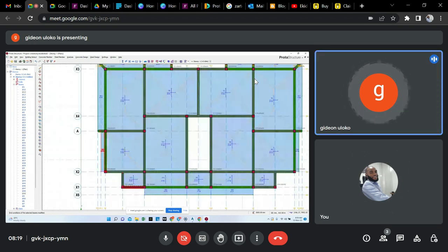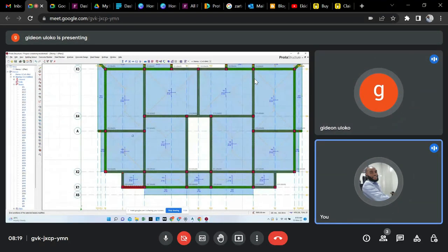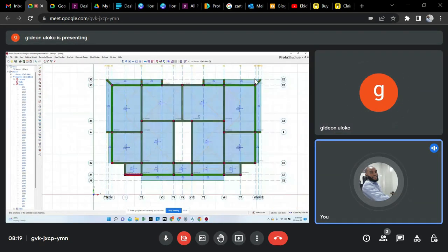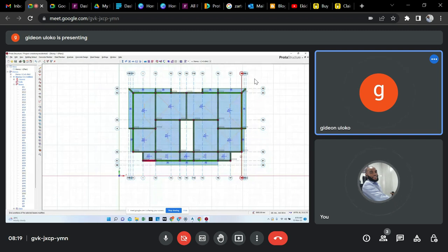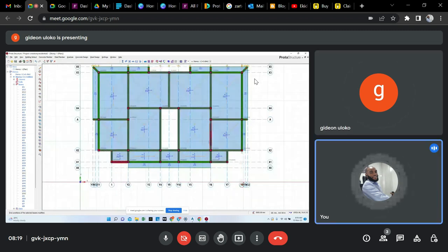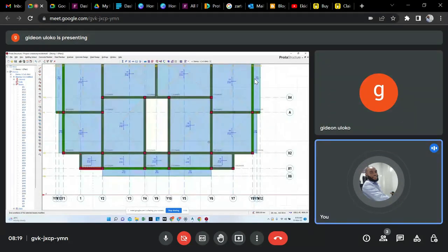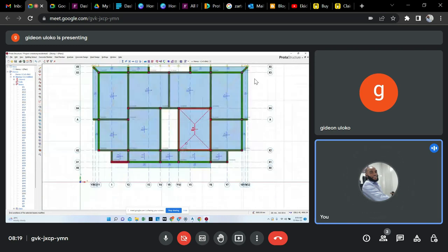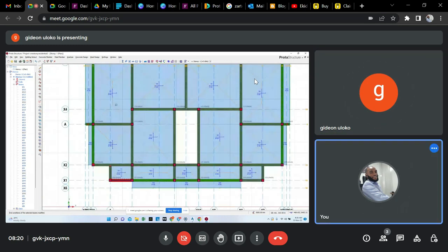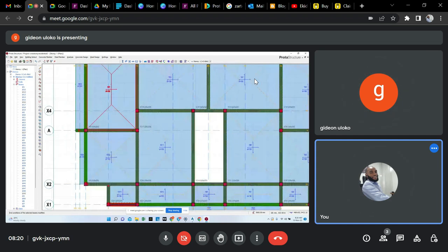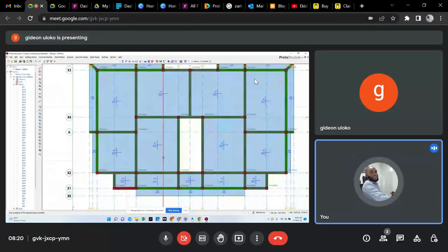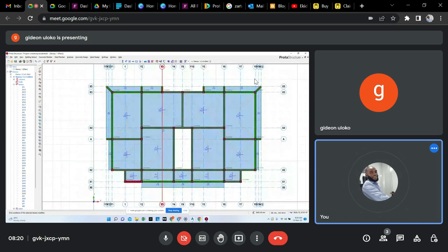Can these cantilever beams hinge? They are not part of it. You don't hinge the cantilever end. But what you hinge now, sorry, zoom out. This cantilever area right now: what you hinge is at the J end, but at the I end you do not hinge because there's a cantilever beam. So right now, select all the ones that are hinging J. Sorry, I end.